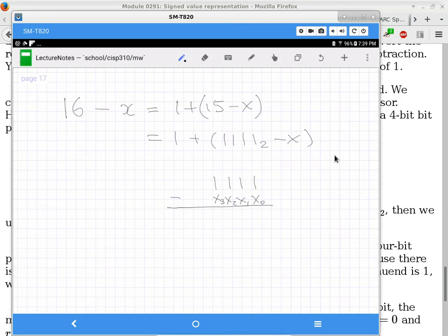Okay. So that means I can now say this is the negation of x0, this is the negation of x1, this is the negation of x2, this is the negation of x3. Does that work? This is a really important part, okay? Does that work? Yes. In other words, instead of using a subtraction, I'm only doing a bitwise NOT. This is exactly what bitwise NOT does. It's not exclusive OR. This is bitwise NOT, which is a unary operator.